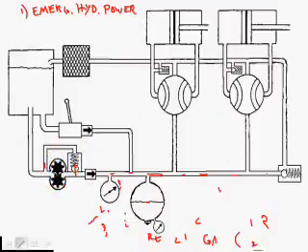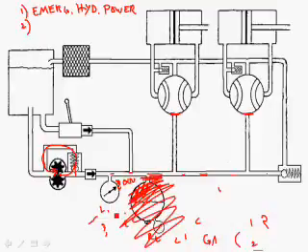All right, next thing that an accumulator can do. Let's say that we're flying along and this selector valve is in the off position, and so the fluid is going around in a circle here, and we're sitting at 3,000 psi. And of course, let's say we don't have an accumulator at all. Let's say all of a sudden we rotate both of these selector valves to the on position, and fluid starts leaving the pressure line and filling up the actuator.